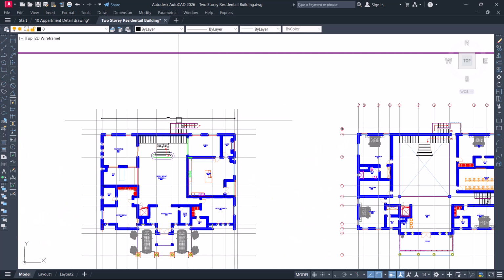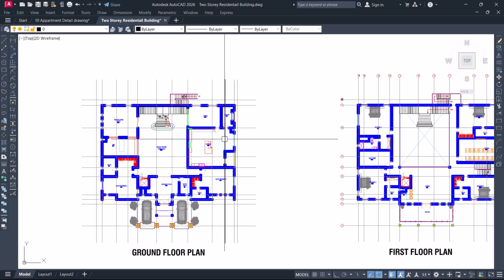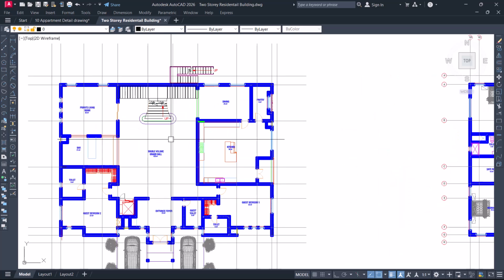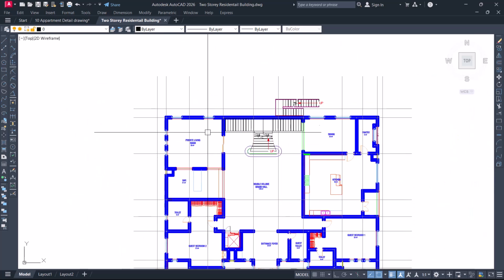Okay, that's fine. So again, I'll just move this dimension now. Since I have known that there is a cantilever on the right hand side of the building, which is this side, we will have to take note of that. So once you want to begin your structural framing, the first thing to do is to understand the building plan, which we have done now, to look out for the features: if there's a lift, where the staircase is, if there's a cantilever on the building, and what the purpose of the building is. In this case, this is a residential building.